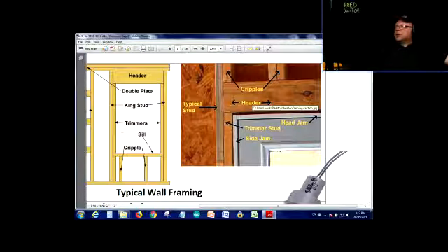Now when you have a residential setting, a beautiful house that's just painted, and they call you to investigate what it would take to install an alarm, whenever I got those types of calls, first I'd ask them, is the drywall on? Oh yeah. Is your house painted? Oh yeah, we just painted that. Well, you should call me a little earlier, because before the house is painted, you can still damage some of the drywall in order to route your wiring, and then you can just patch it up and paint on top of that.